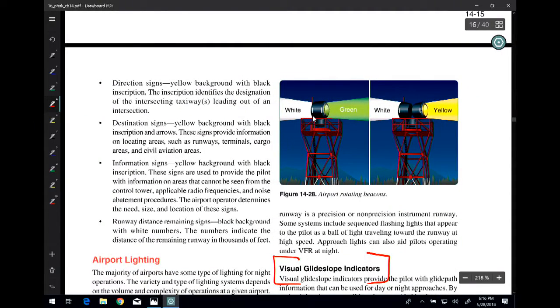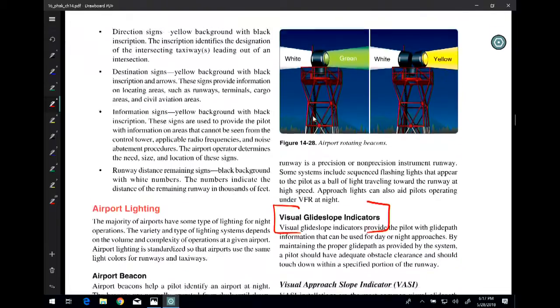So depending upon your position, if your position is stationary, it will rotate and it will kind of flash. It's a relatively narrow beam that emits from these beacons. So it'll be kind of a flash. And so you'll see this white flash, green flash, white, green, white, green. And that'll indicate a civilian land airport.